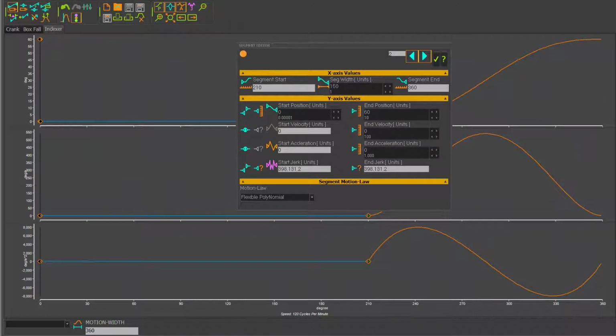We can also change the mathematical functions that calculate the y values for a given machine angle. These are sometimes called motion laws. Changing the motion law varies the ratios between the peak amplitudes of the derivatives, and it also affects the distribution of frequency amplitudes that can be decomposed from the time series by frequency analysis. Generally, we need to keep the power in the lowest possible frequencies, although motion laws with low frequency content tend to have higher peak values in the derivatives.